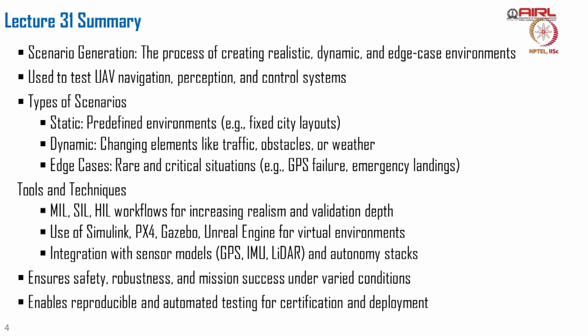We talked about different tools and techniques for this. Model in the loop, how we can model the entire flight control architecture. Then we can bring in software in the loop, and hardware in the loop workflows, which help us validate the control law or algorithm you are developing, whether it is implementable in real time.